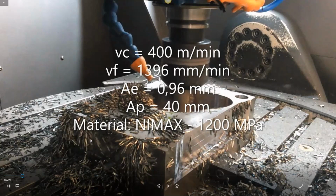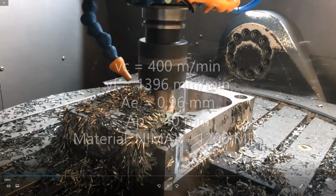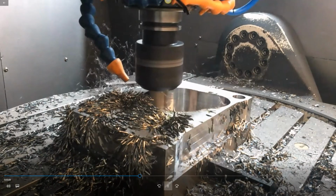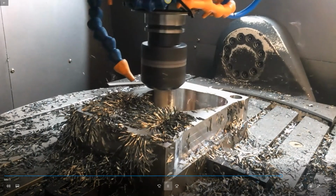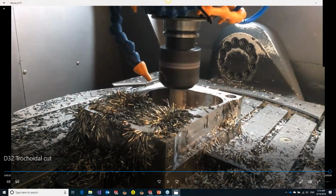If you want to use an insert cutter with iMachining, you should have a different geometry for the inserts and the insert cutter than what you would use if you're doing smaller step overs. So here's a short little video. You can't hear the sound, but this is tool steel, and this is using iMachining style cutting with a custom tool developed with ISCAR. You can also see that the cutting is currently dry, which is really impressive.